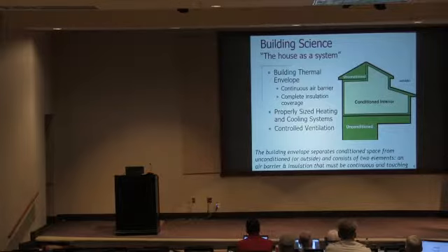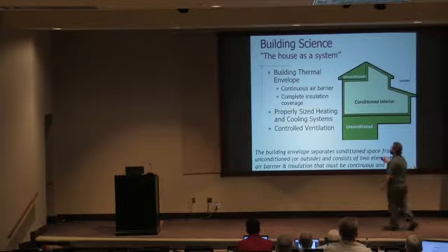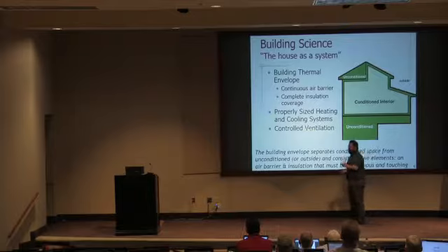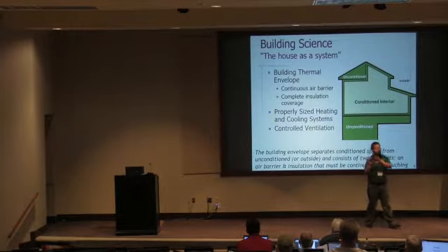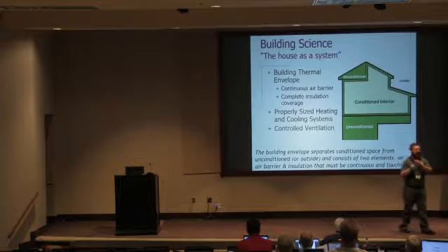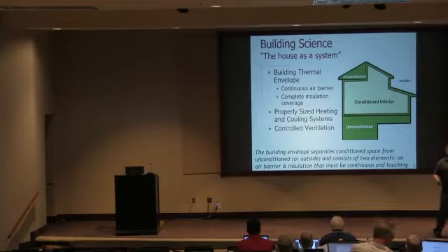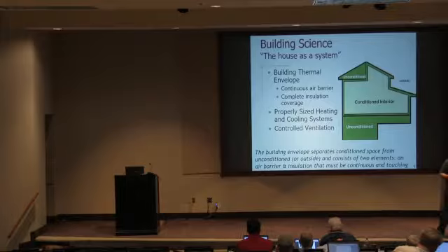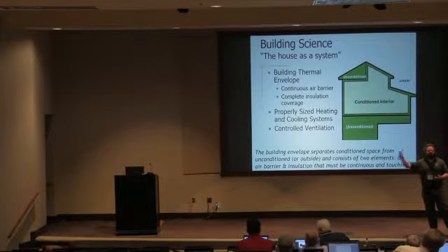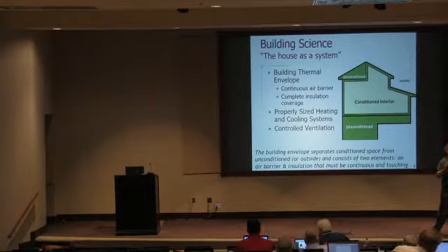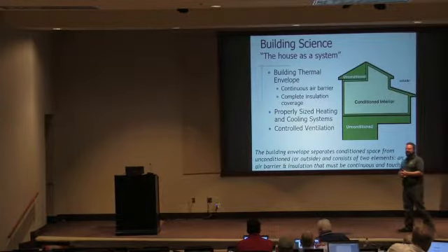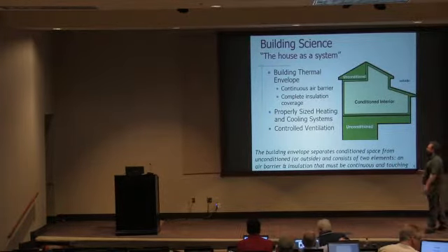So what we're trying to do from a building science standpoint is eliminate uncontrolled leakage by creating a perfectly airtight and insulated thermal boundary. Then we're trying to reintroduce controlled ventilation so we get to know how much, where it comes from, and when we ventilate that home. That gives us the best of both worlds. Adequate ventilation for indoor air quality and human comfort, control of air changes for energy efficiency and for good IAQ, and a home that actually works well. It's comfortable inside, has good indoor air quality, and provides the fresh air ventilation that we need for human occupants.